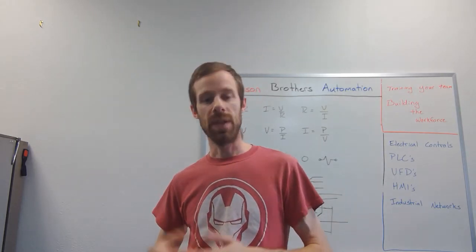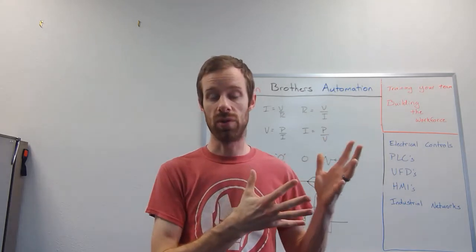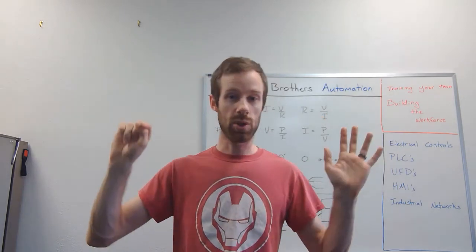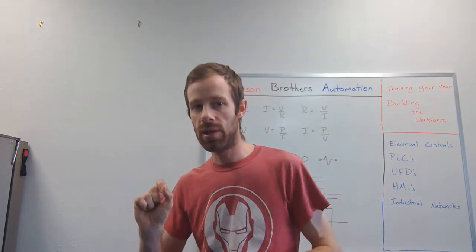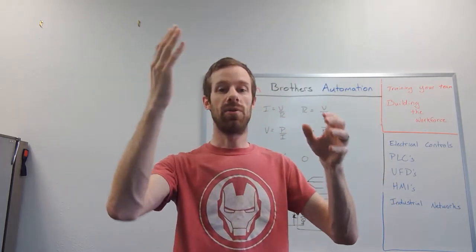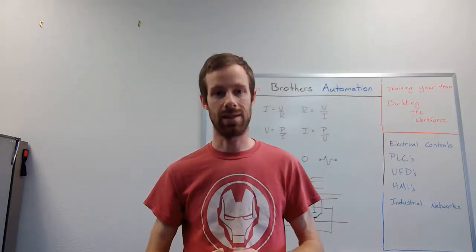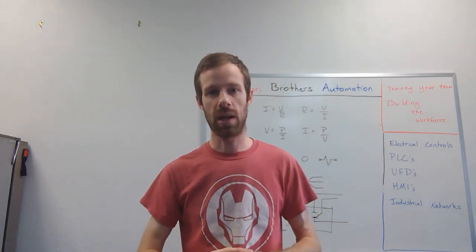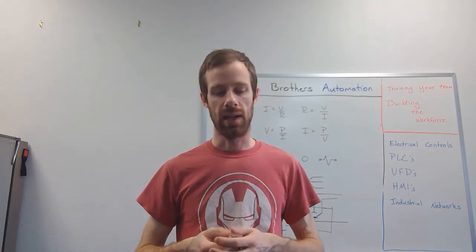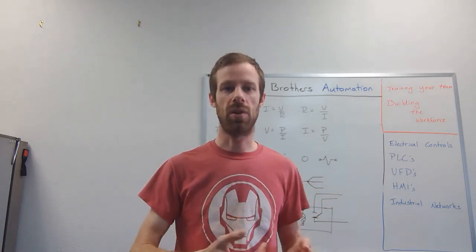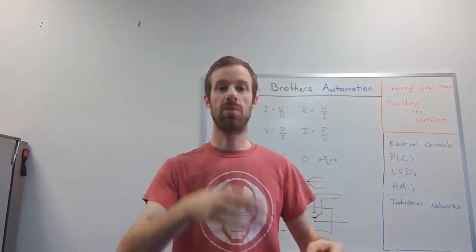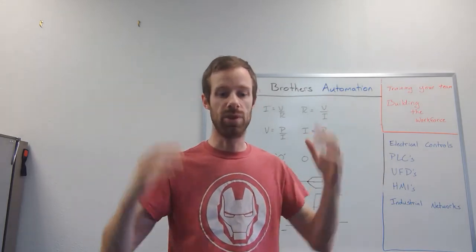But their whole job is going to be to get the dangerous voltage levels to a place where the operator doesn't have to touch that dangerous voltage level at all. The operator can push the go button with only a tiny little voltage. That tiny little voltage activates a load device. That load device then allows the huge voltage to run the huge devices like big, huge motors and heaters like we were talking about, but these heaters can be like 240 volt, multi-thousand watt heaters. So these load devices are often meant to keep the operator safe and allow the bigger voltage to be off in a different place to allow the large current to flow to make the huge devices run.